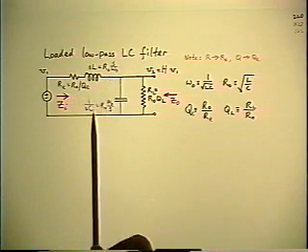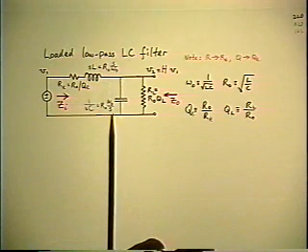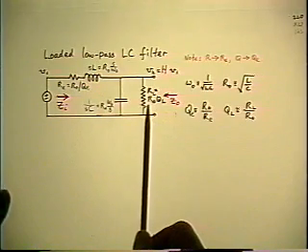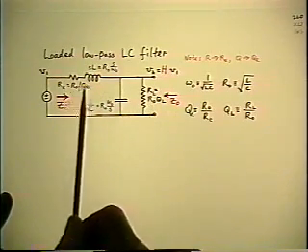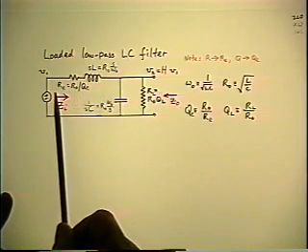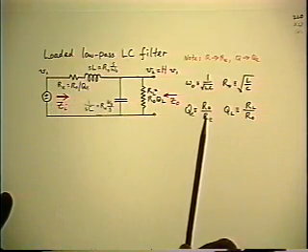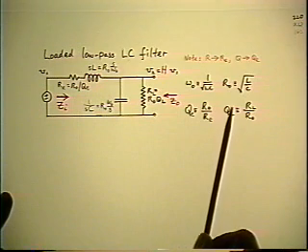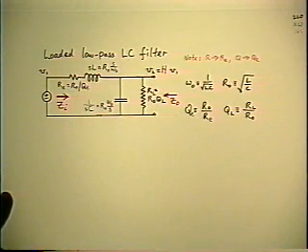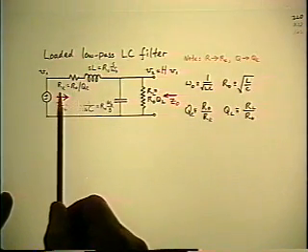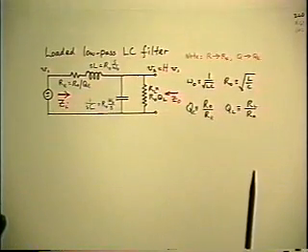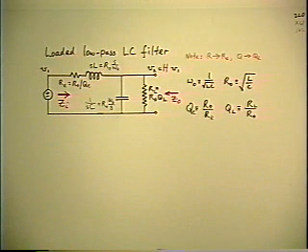So the SL and the 1 over SC are just as they were before. Do the same thing with the resistance, but there's one more difference now. We're going to be dealing with a second resistor. So I've put an extra subscript on the first resistor and on its corresponding Q factor, just so I can relate the Q directly to that resistor, because I'm going to have an additional Q factor now. And I want to keep the Q without any subscript as being the general quantity. So I put a sub E on the original RE and on the corresponding QE.